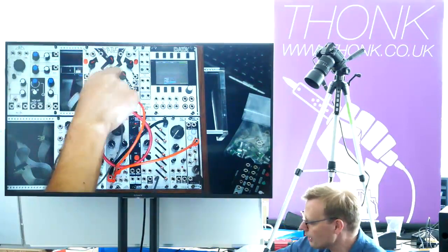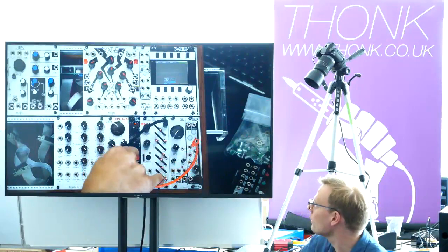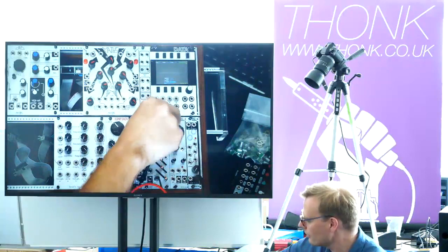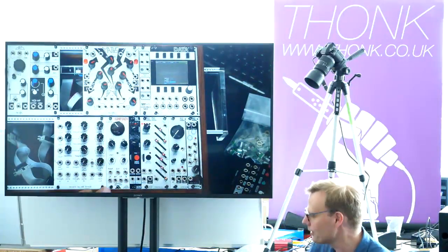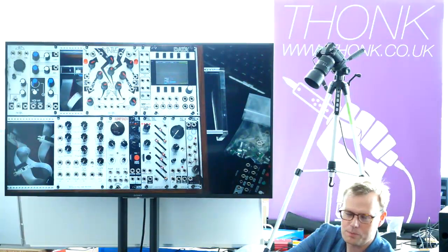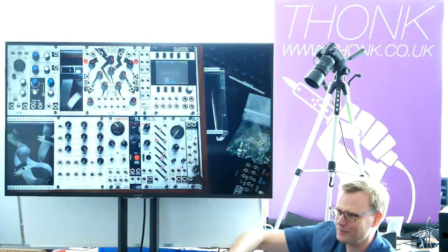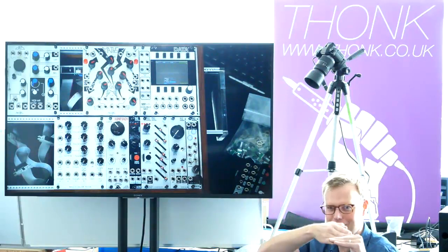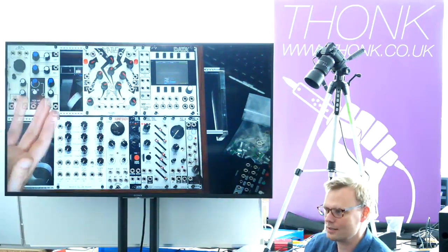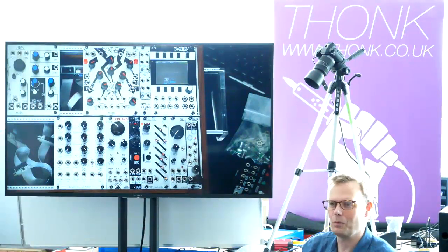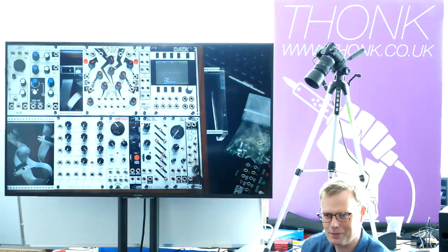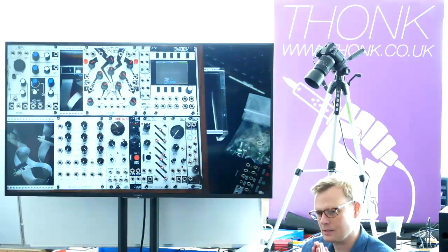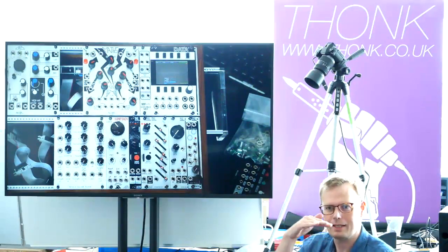One of the things that I mentioned earlier was phase, and we're going to try and demonstrate this on the oscillator, but I think it's not quite working as we hoped. So if you imagine your sine wave is going like this, a simple sine wave like that. If you take that sine wave and invert it, it goes the opposite way. Now, if you just listen to that normally, it won't sound any different. A sine wave that's this way up, a sine wave this way up doesn't make any difference at all. But if you mix those two signals together, they cancel each other out.